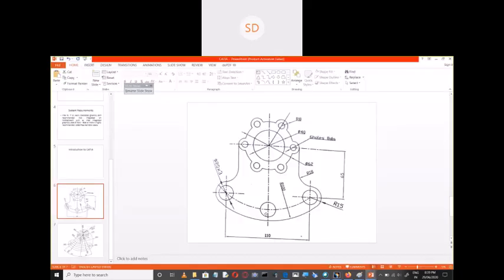Now to place this particular circle, you need to draw an arc which has a radius of 100 here. So now this arc center point is from this center point. Arc point for this one is from this center point. Now we need to draw this pitch circle arc here. Pitch circle arc. Now what is the diameter? Sorry, what is the radius? It is 100 minus 15. You will get 85.